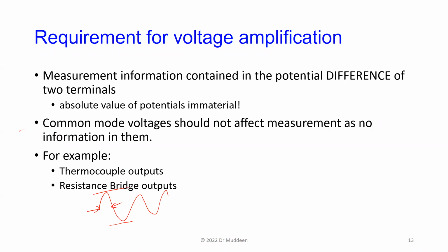It's a 60 hertz signal, and the voltage is quite large. If you were to put probes on, for instance, when you're taking heart or muscle measurements, those very small voltages, what happens is that if you watch it on the scope, it actually looks something like this. Right? So there's this big 60 hertz thing.